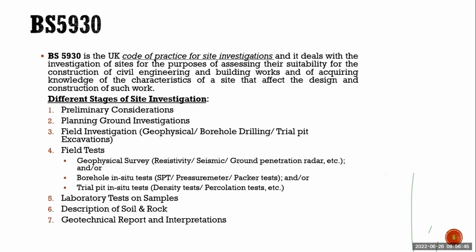Now let us say I am party A, and instead of using the 63.5 kg hammer, I use a 100 kg hammer to make sure the soil is very stiff. Accordingly, we will know which particular layer has a strong, dense soil. In my perspective it is right, but as per the standard it is 63.5 kg.